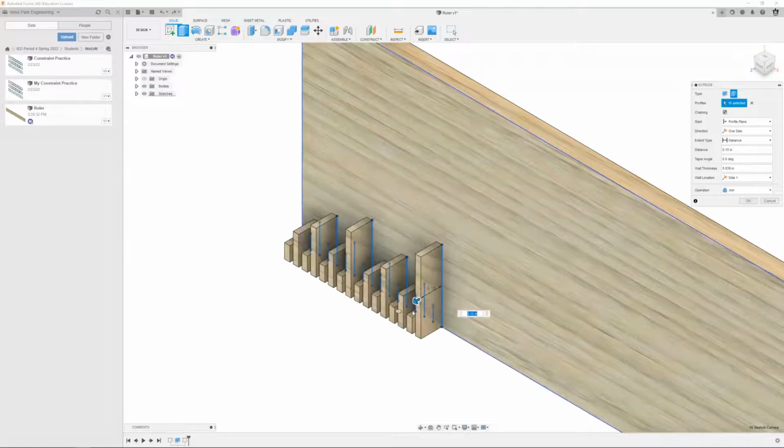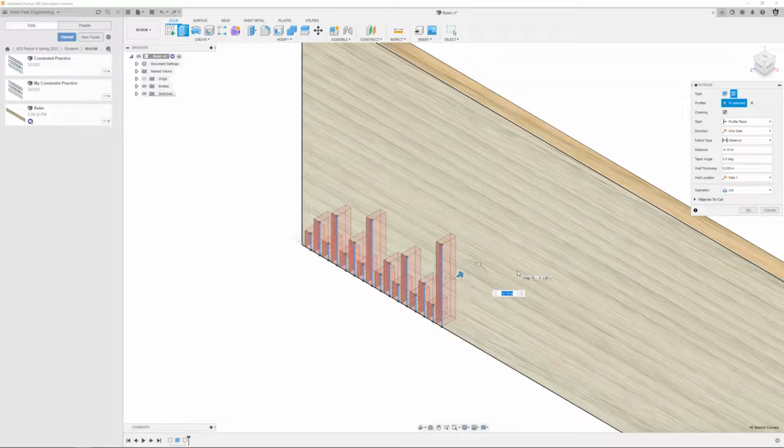We can go out. That looks neat, but the laser cutter can't do that. We've got to go in. And the number we're going to use, notice it's negative now. We're going to use minus 0.005. So that's how far it's going to cut into the wood.